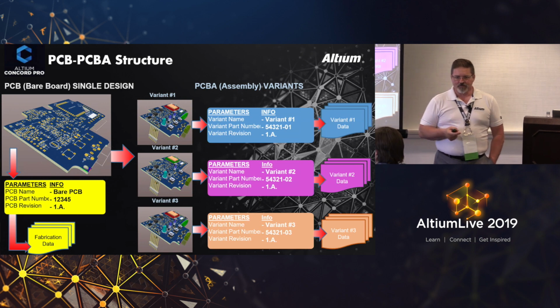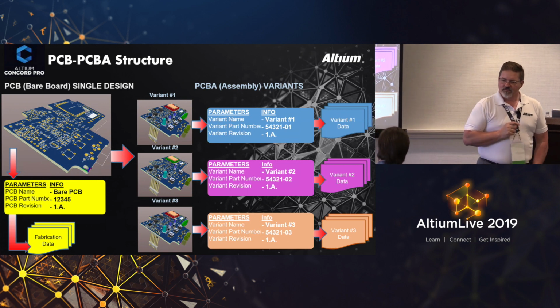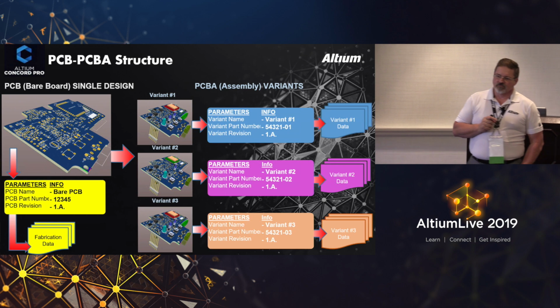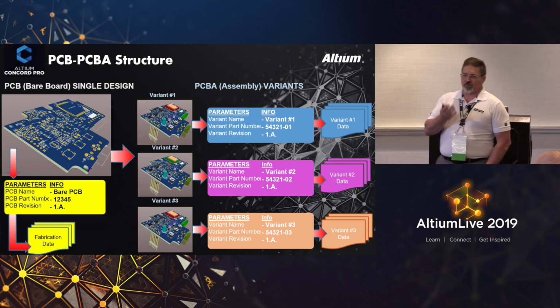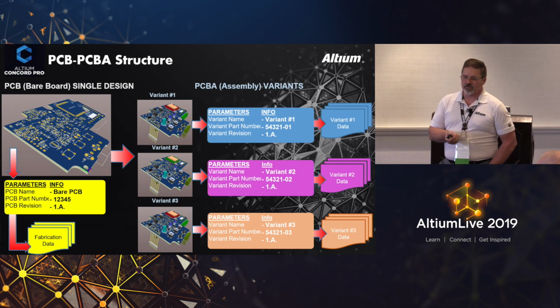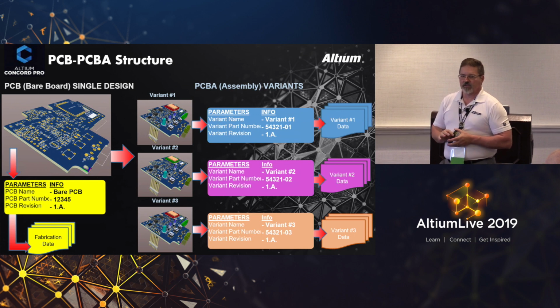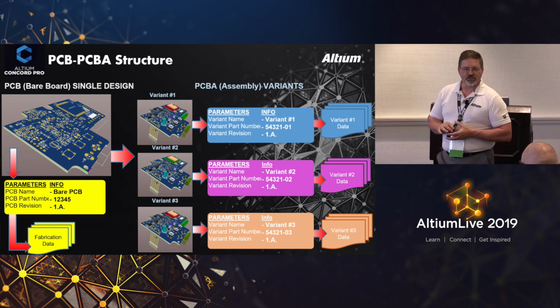So what would be 2B? Like not necessarily changing the copper, but say putting another mount hole on the board or something? No, okay, let's say you're putting a new mounting hole. Not copper at all, but they just need to move the one hole up. Okay, so if you move a hole, would that mean new Gerbers? Yes. So that means you would be bumping the major revision.